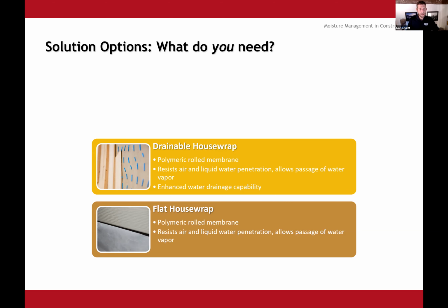So that's where you get to having that 1 millimeter compression-resistant space that lets water drain from behind your siding. So it's going to do all the same things, but bulk water can also get out. And I'm going to encourage most of you to use a drainable house wrap as your default spec. It's just safe. It's just good building science, and it's really going to protect you in a lot of cases. And that's the better. Now, the best option is going to be rainscreen.